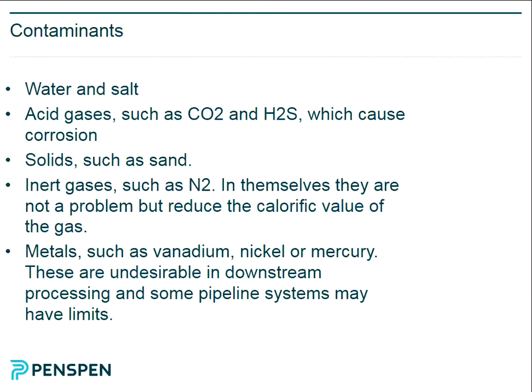So solids, such as sand, you'll find in the reservoir. If it's a sandstone reservoir, in some reservoirs you can get sand produced. And the problem with sand produced is that it ends up in separators. Quite hard to deal with. Sometimes you have to shut the separator down, enter it, and dig out all the sand. But also you can get erosion as well. Whenever you get a bend, you'll get the sand particles impinging on the bend, and it's actually possible to cut right the way through a bend. So sand is not good.